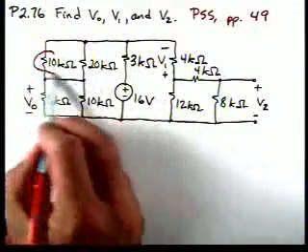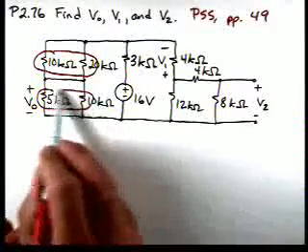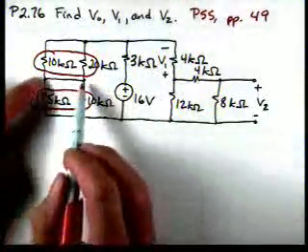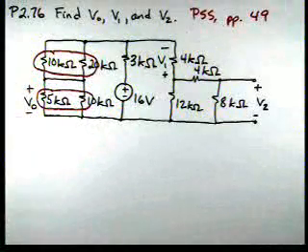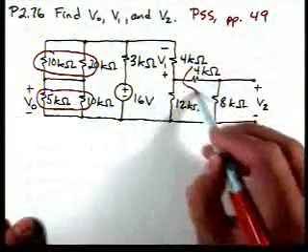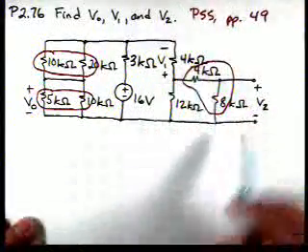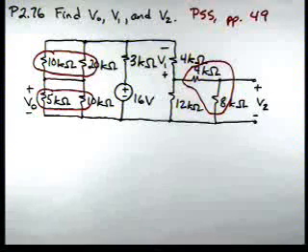These two resistors are in parallel by the way they're connected, so you could think about taking these 2 points and squeezing them into a single point. Another thing is, if we look over here, those two resistors are in series. We're not going to worry about V2 yet. We're going to solve for it along with V0 and V1. So the first thing to do is start reducing that network down.